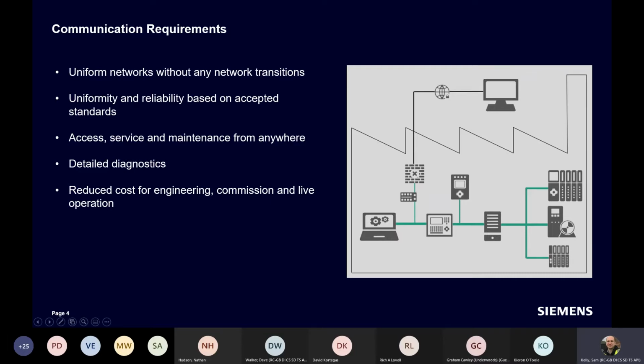So we don't necessarily need to have a specialist laptop which has, for example, a Profibus port, or indeed you may need to purchase a USB to Profibus adapter or a PC adapter, MPI adapter, that type of thing. So having that uniformity there is very good.